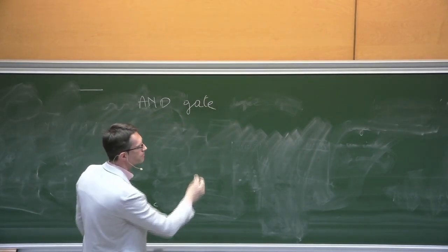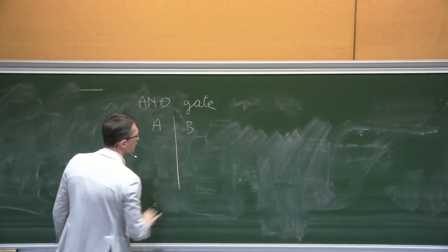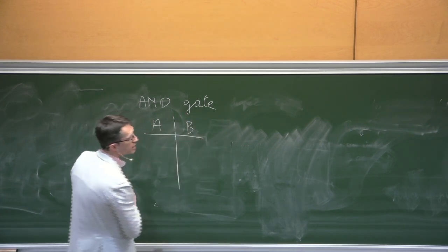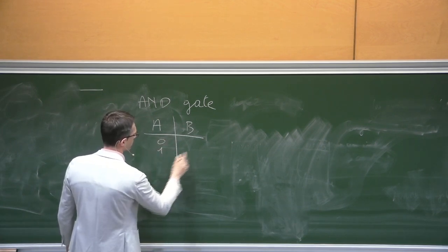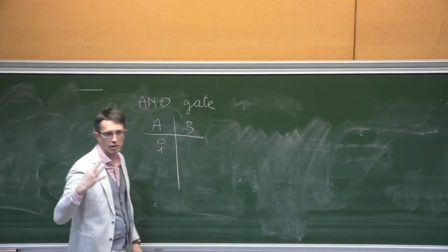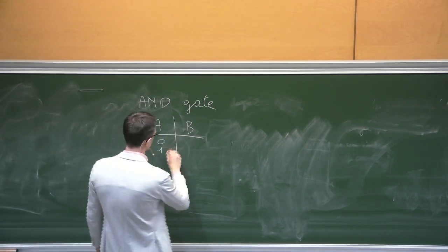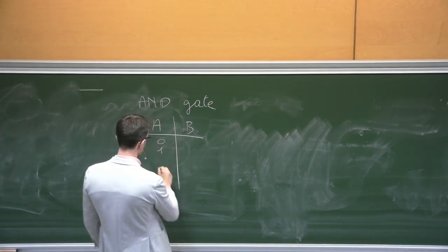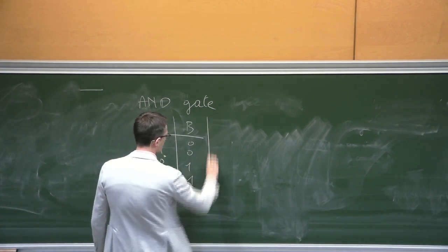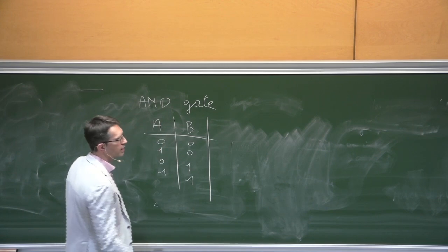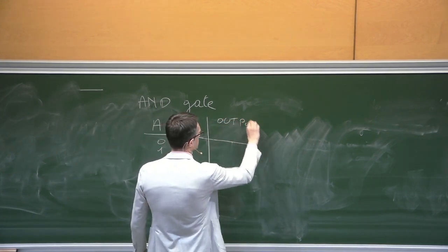So typically, you have your bit A and bit B. A can take 2 states, 0 and 1, and B also, so like we said, 2 to the power of 2, so 4 possible outputs. So we write 0, 1, 0, 1, and then the equivalent will be 0, 0, 1, 1. Okay, and then you make the output, which in this case is the AND gate.